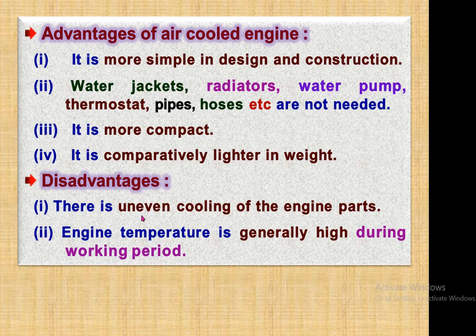Now some disadvantages. First, there is uneven cooling of the engine parts. Whatever parts are just near the fin system or near the fins of the flywheel cool more, and the other side, or we can say the opposite side, will cool less. So there will be uneven cooling of the engine parts. Second, engine temperature is generally high during the working period.